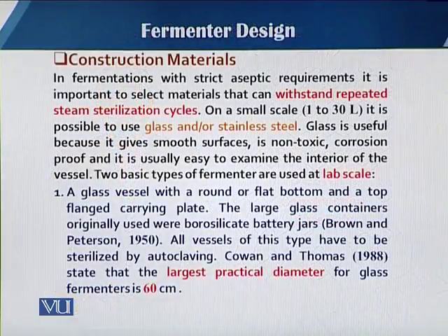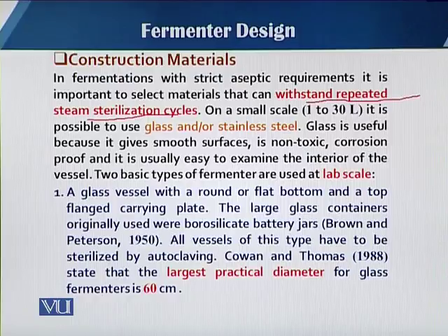Here we will see that there are different options that can withstand repeated steam sterilization, because in the general organization of the fermentation process, for aseptic operation we have to sterilize the fermenter either in situ or ex situ. In the case of a lab scale fermenter, we sterilize ex situ by putting our fermenter inside the autoclave. But in the case of pilot scale and industrial scale, we have to use the in situ sterilization process.